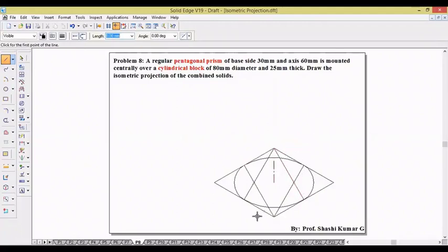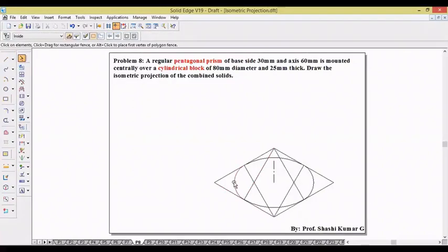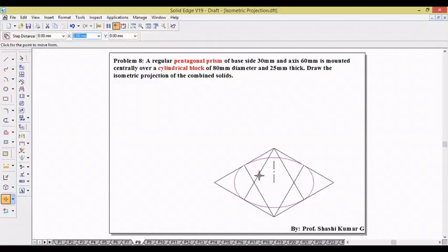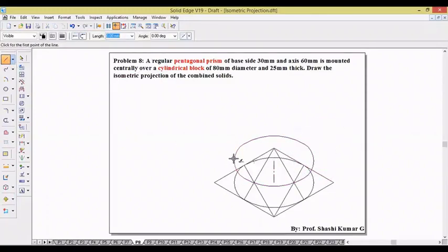So just choose the bottom ellipse, keep control and choose the arcs of the ellipse and move, switch on copy from base to the top. Join the tangent lines to complete the cylinder.